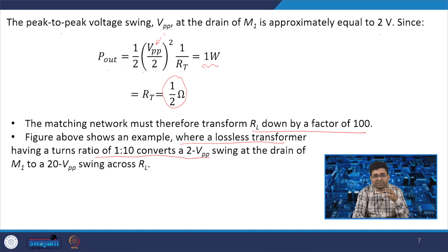We should have a matching network which can also help us to transform the lower voltage swing to the higher voltage swing. However, the amount of current that is experienced by the transistor is always high, and the on chip transistor should also withstand that much current.